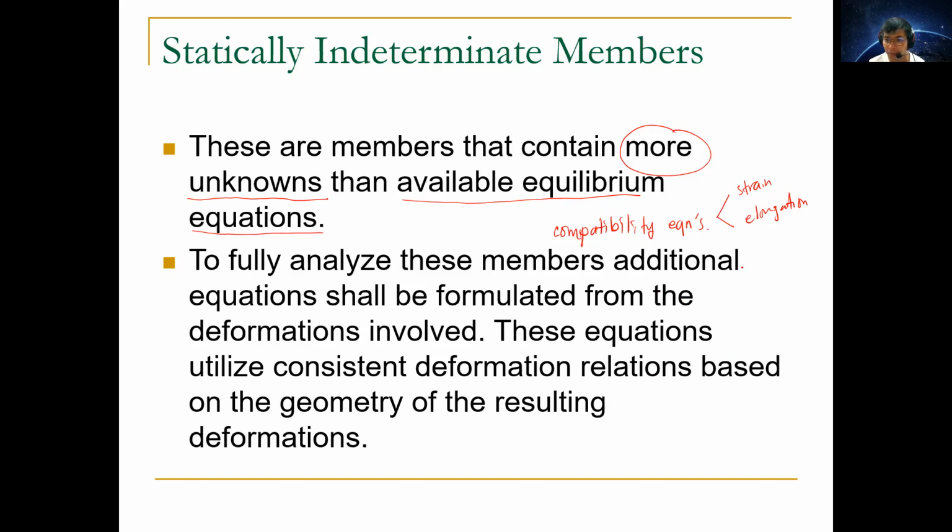Okay, so most likely the popular formula that we utilize more is the elongation, which is small delta equals PL over AE. So this is what will most likely recur in our different problems. Okay. So again, we utilize these compatibility equations for us to create another geometry that will result to the forces of your members being solved.